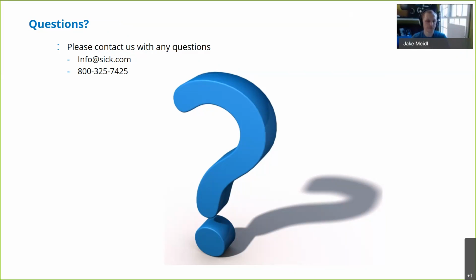Awesome. Question comes from Vivian. She asks, what are the differences between the IO-Link master and SIG 100 master? When do you choose one or the other? Yeah, it's a great question. So the SIG 100 shouldn't be called a master. It should be called a hub or a slave module. SIG 100 is just digital I/O.